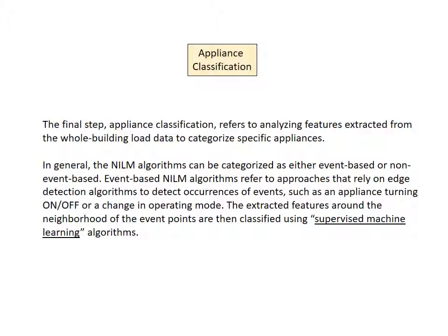In that case, we're relying on having an existing library or database of real and reactive power consumption for different devices, or their transient signatures in terms of their voltage or frequency. So we're talking about algorithms that we categorize generally as event-based or non-event-based, and we're just going to talk about event-based. That refers to approaches that rely on edge detection.